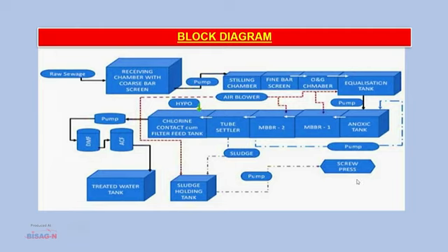Then stage 9, the anoxic chamber. An anoxic zone is created by using an unaerated tank where the dissolved oxygen level is kept below 1 mg per liter and as close to, without reaching, 0 mg per liter as possible. A target operating point would be between 0.2 to 0.5 mg per liter.